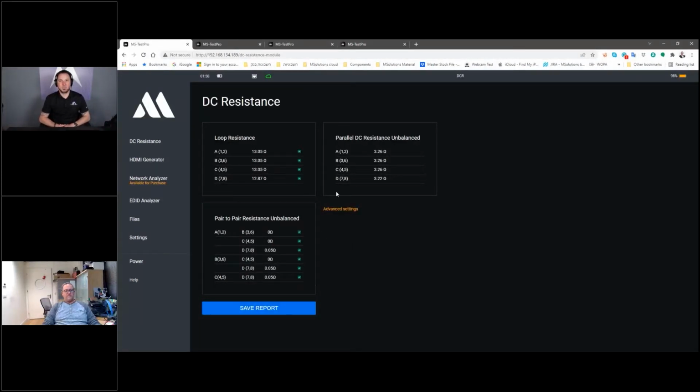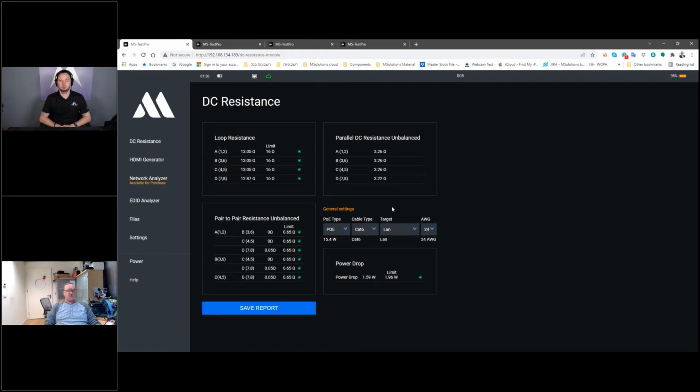And this explains exactly what goes on the cable and why the quality of the cable is important. What we did at MSolutions, we actually improved the way that we are looking at the cable. Because HDBaseT, for example, is an asymmetric link, means the bandwidth from one side, from transmitter to receiver, is very high, but the opposite direction is a very low one.